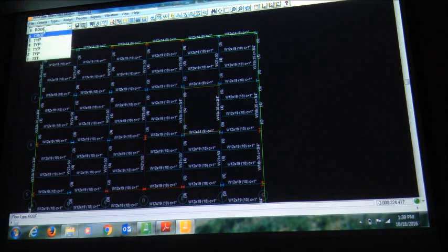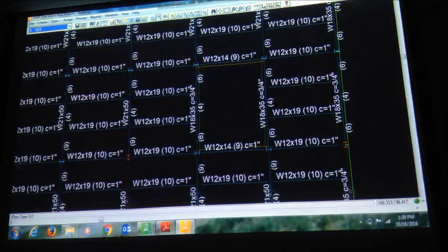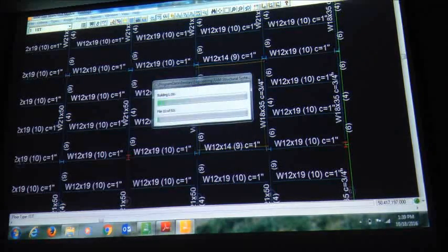Is the camber accounting for the live load too? Usually cambers are calculated based on the dead load. Live load is not that important. Look, your dead load is 80 pounds plus additional. Your live load is 40 pounds plus its reduction, so it's about like 30 pounds basically. And live load is here and then it's not there. So camber is only for dead load. And what about the first floor? Well, first floor doesn't have any changes, so same. Okay, so beams are done.